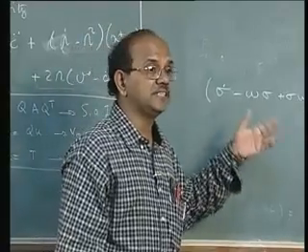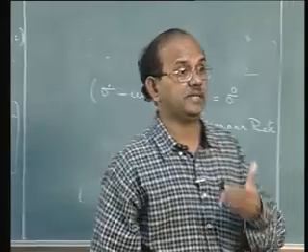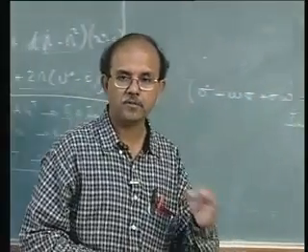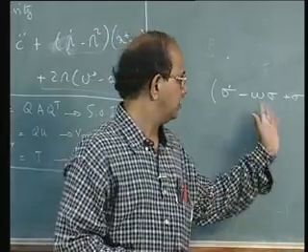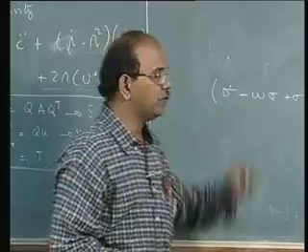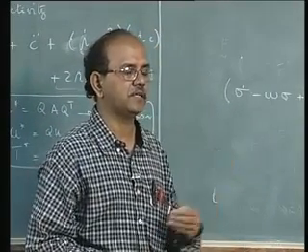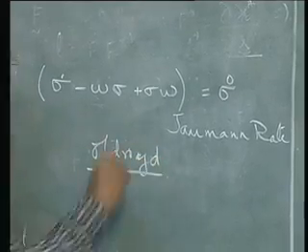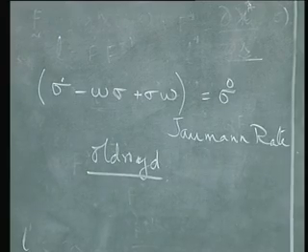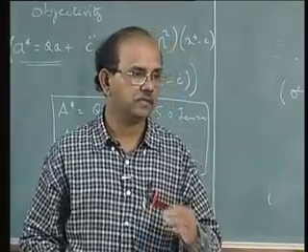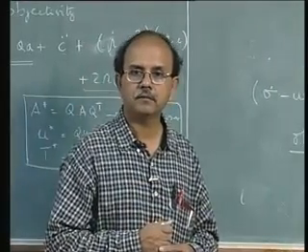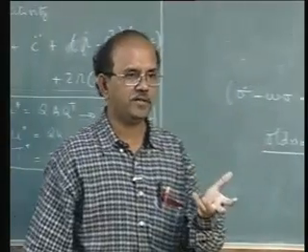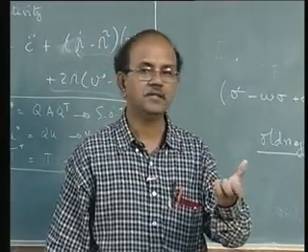So in this sense there are a number of objective rate quantities. These quantities are used as one of the members of the constitutive equation. You can check this. But even before we do that, to give a physical picture of these rate quantities, let us look at what is called the Oldroyd rate. Oldroyd rate is a Lie derivative of sigma. What is a Lie derivative? We had already seen this. Pull back, do a d by dt, then push forward. That's called Oldroyd rate.